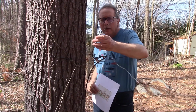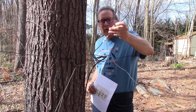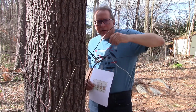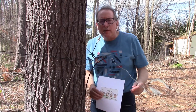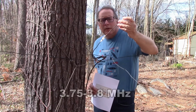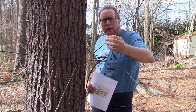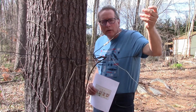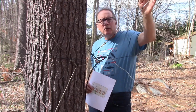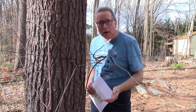Okay, we've got our ground plane. We've got this little alligator clip, because I know I'm going to have to shorten it up. I'd like to bring this antenna up into the phone band around 3.75, the DX window, the single sideband window, 3.7 to 3.8 megahertz. So that means we're going to have to take off a little bit of length, which I'm counting on, because I'd like to get this thing up a little further.